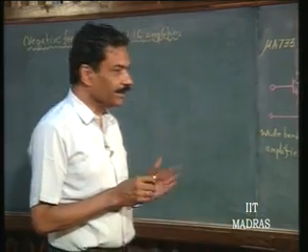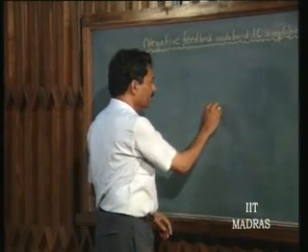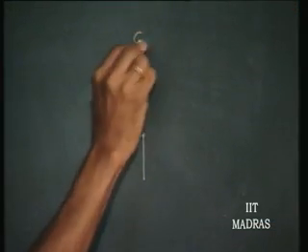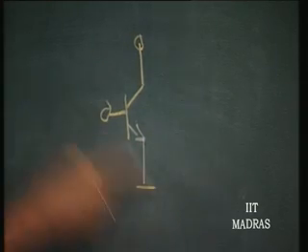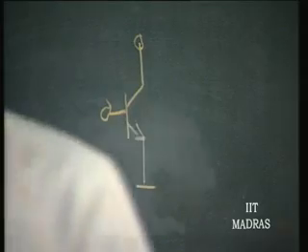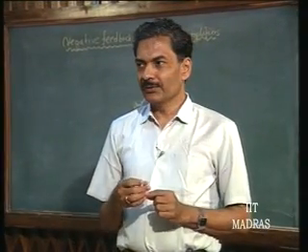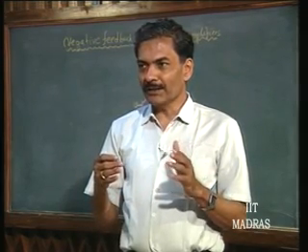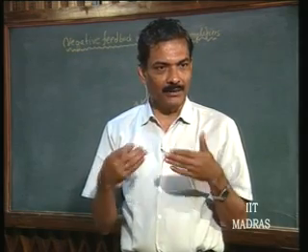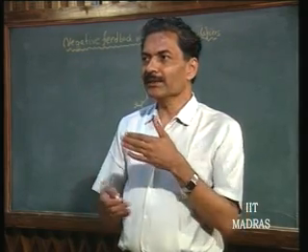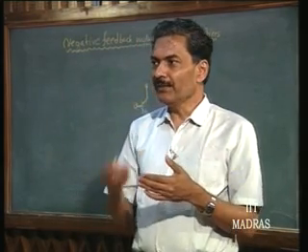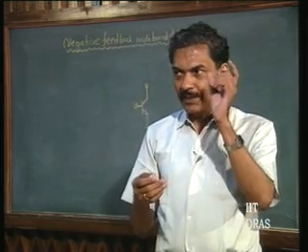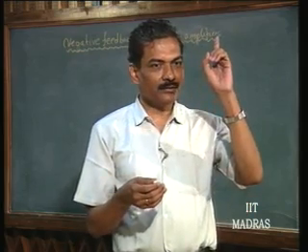But we know that a single stage amplifier, for example a common emitter amplifier, has 2 time constants, input time constant and output time constant. So, the minimum order of a single stage itself is going to be 2. So, if we cascade more number of stages, we are landing ourselves in more problems, because the order of the system will increase above 2, it will become 3 or more. Further, the loop gain is also going to increase. The consequent need for frequency compensation becomes more serious there. Therefore, the best negative feedback configuration for widebanding is a single stage.